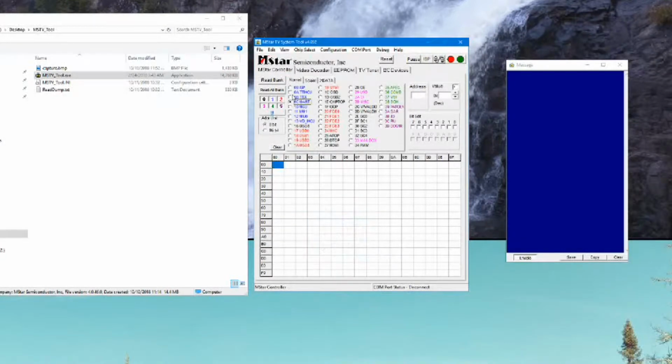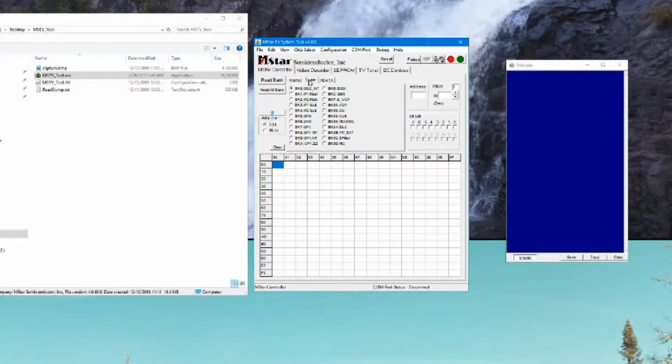So by selecting these values here, down in this spreadsheet-looking area, it'll actually pull up the values for these different menu items basically from the firmware. So here, for example, OSD: the first couple bits are the color of the on-screen display as well as transparencies and things like that. PWM has to do with whether there's a backlight driver, the PWM frequencies of that, as well as all sorts of other fun goodness inside of here. Again, most of it doesn't apply to the chip that we have, but for things like 3D noise canceling and upsampling for a composite, you can actually see the values in here changing as a composite input changes, which is interesting. So again, here's more values you can pull in from the actual DSP of the chip.